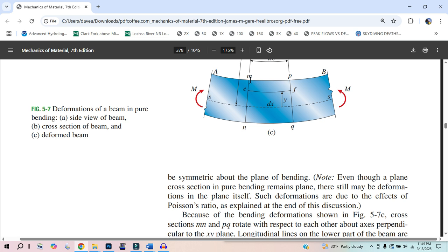If we have a meter of something and you pull on it to where it gets to be 1,002 millimeters, that's as much as you can lengthen it before people die, let's say. That's just the linear range, but we design basically everything to have plenty of strength, so throw a factor of 2 on it and just stretch it to 1,001 millimeters. So that's kind of the premise there.